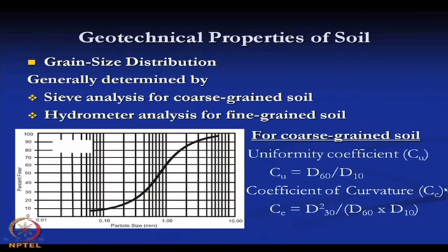Similarly, the coefficient of curvature is defined by D30 square divided by D60 into D10. So, from here you also get the two coefficients.